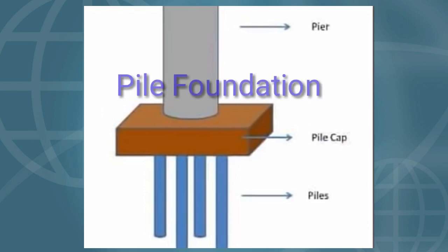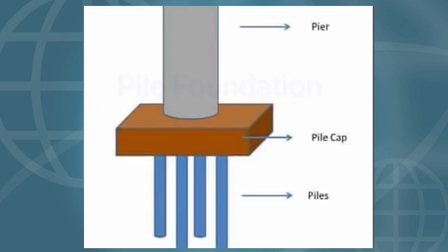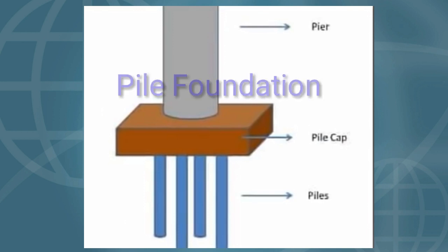And another situation is when a building is very heavy or has concentrated loads, such as in a high rise structure or bridge or water tanks. Whenever this type of situation comes, in such situations we use pile foundation.